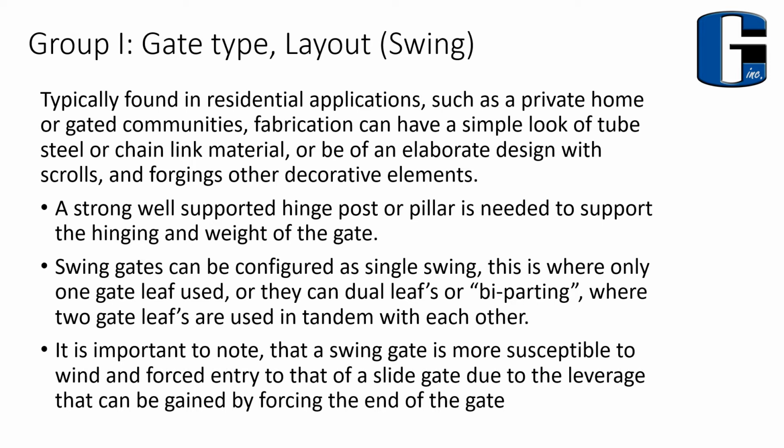It's important to note that a swing gate is more susceptible to wind and forced entry. Think of a swing gate as a big long lever. So compared to a slide gate, due to that leverage, a lot of force can be applied to it, whether it's someone trying to force the gate open, or a car or vehicle tagging or hitting the gate, or even wind can do things like that, damage to it.